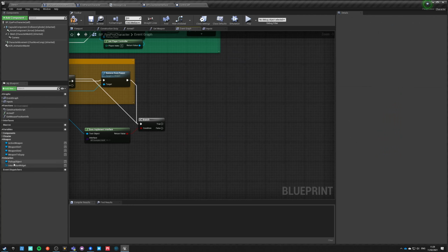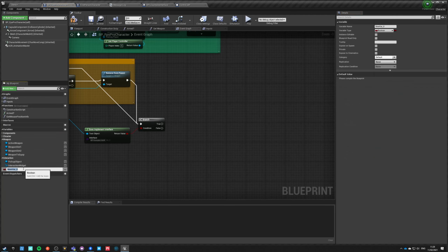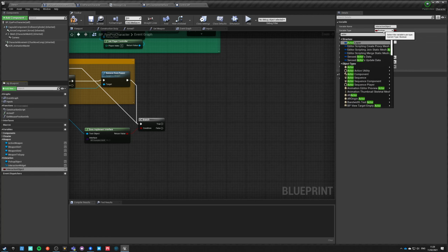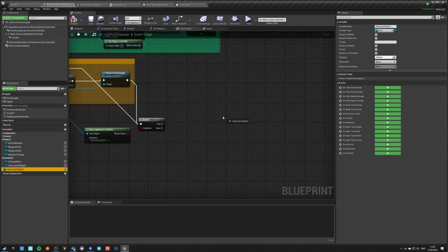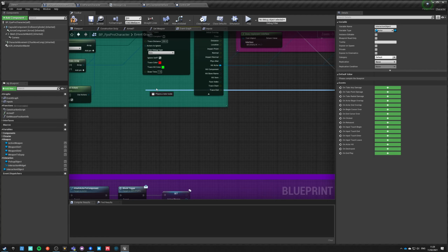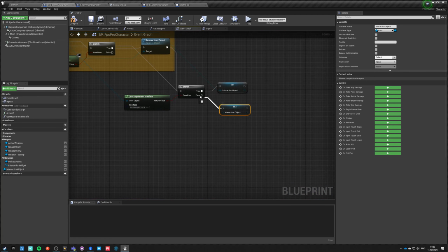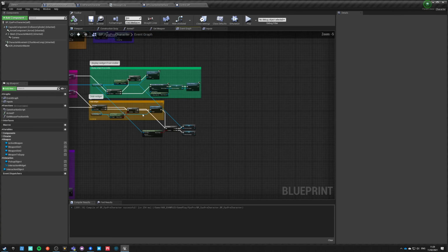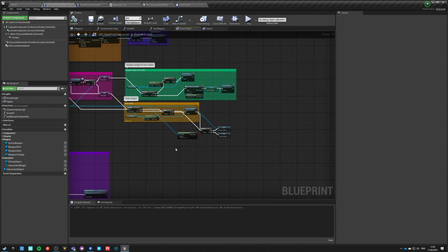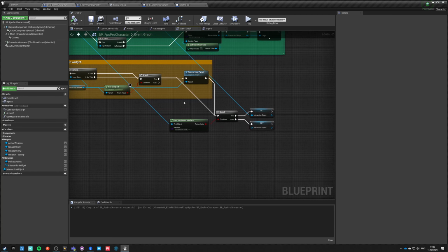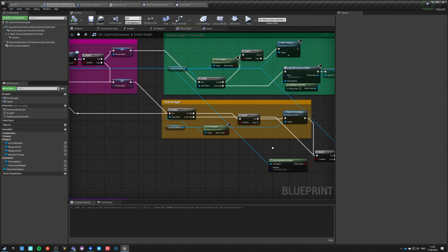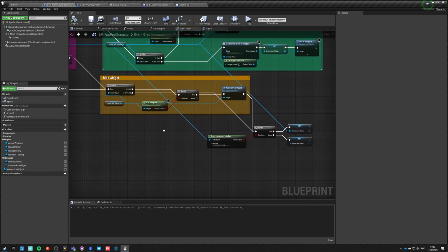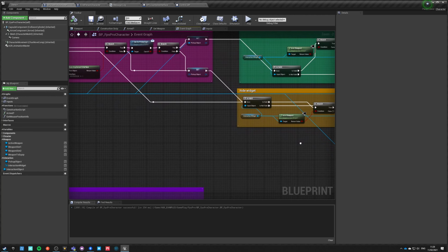Or maybe not pickup object. Let's make a new variable, which is an actor, and interaction object. And this will be an actor. We don't have to use the same variables for everything, right? And just set, and if it is true, then set it to this actor, and if it is false, then set it to nothing. Okay. And we're not doing anything with tooltip here because that's just a waste of our time. We would have to do it in similar fashion, or just modify this tooltip to be also interaction tooltip. But we're not doing that, and that's it.